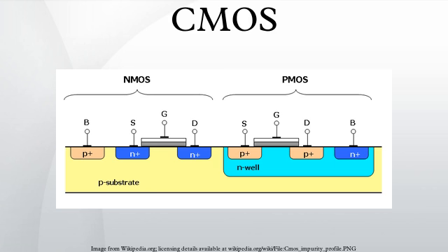Short-circuit power dissipation: since there is a finite rise and fall time for both PMOS and NMOS, during transition, for example from off to on, both the transistors will be on for a small period of time in which current will find a path directly from VDD to ground, hence creating a short-circuit current. Short-circuit power dissipation increases with rise and fall time of the transistors.